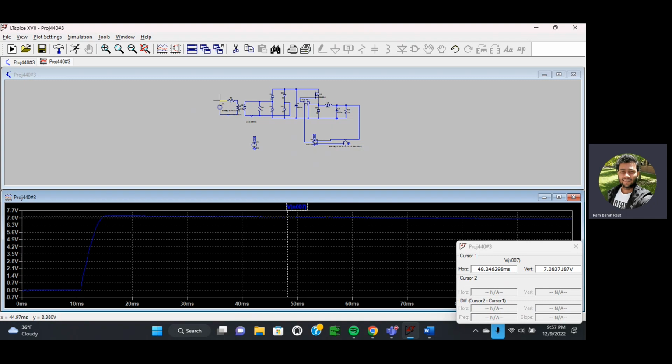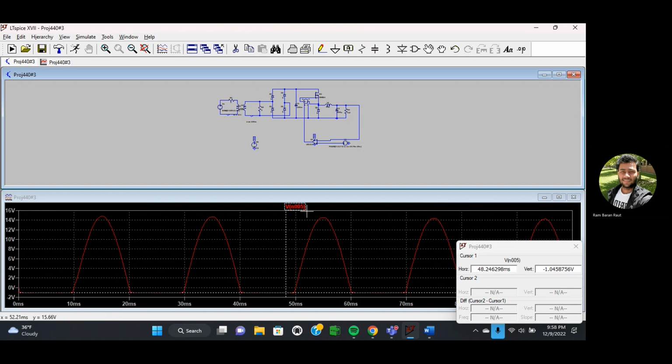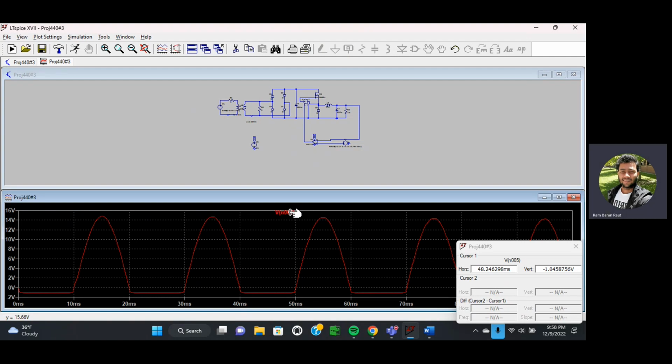To see the effect of changing frequency, we can plot the input voltage. You see, last time we had this, where one period was over here, which is 16.7 millisecond. Right now, one whole cycle of the wave is over here at 20 millisecond. So this is the period, 20 millisecond, for the frequency of 50 hertz. Everything will be the same.